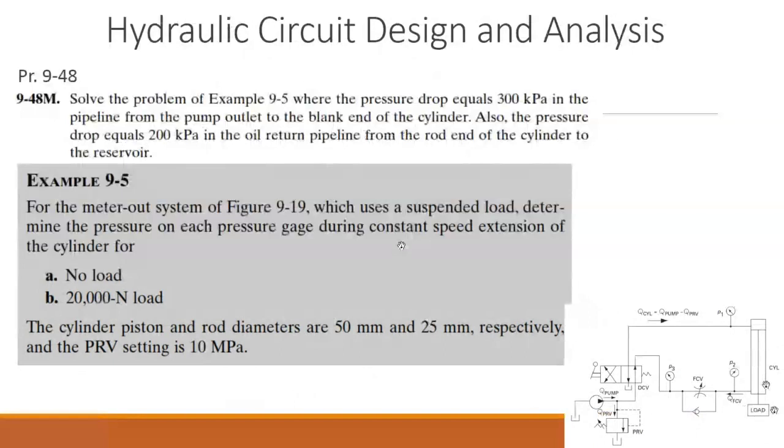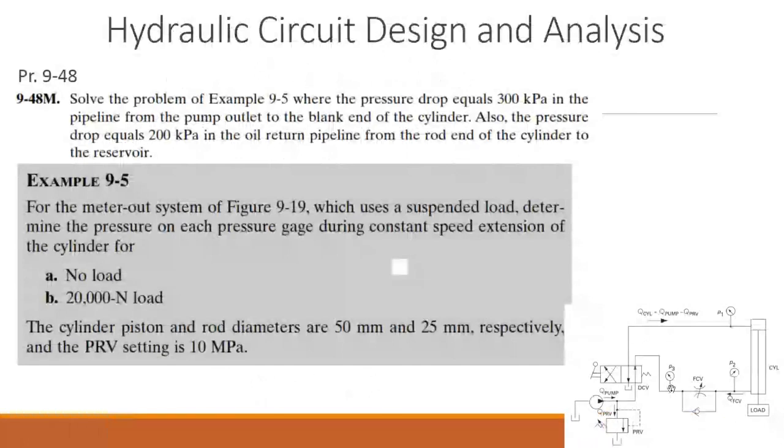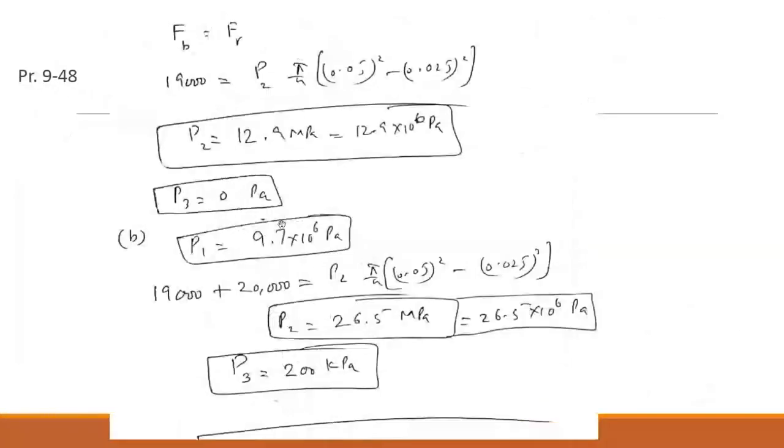Okay, remember that it's just because of this hose setup. This will be the pressure developed at the rod side. What about P3? P3 is simple. P3 is just next to the tank, so it will be zero gauge pressure. Here we go. Done. So that part is done.